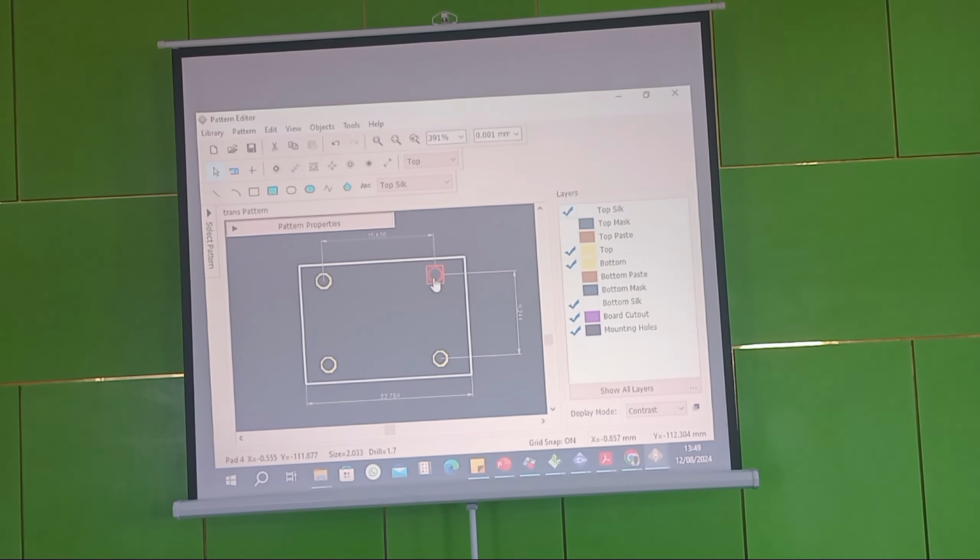This is very important. Pattern. When you are creating your pattern, the pad number or the pin number is very important. You can scatter the pin number or the pad number on your graphical symbol. Even though if you scatter it, when you are trying to merge it with the pattern, you will correct it. Do you understand what I'm saying? In your graphical symbol, let me explain to you.